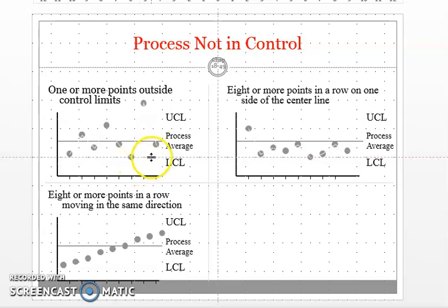And this type of process control chart happens when there are errors in measurement or calculations made by the supervisor, the samples are chosen at a peak position of temperature, pressure and such other factors, there may be wrong setting of machine and tools, or the sample is chosen at the commencement or at the end of the operation. Then this type of chart pattern will happen. That pattern is called extreme variations.